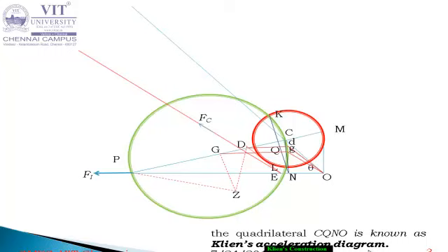This Fr may not give any inertia force component, but it is used to find the intersection point I, that is the instantaneous center. To find that instantaneous center I, this component is used. So this will be taken as Fr, the inertia component acting on the opposite side of the crank force.